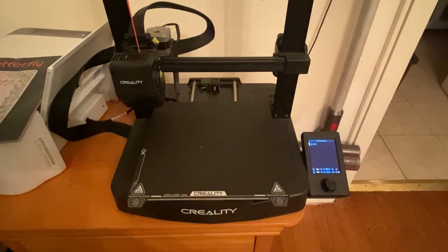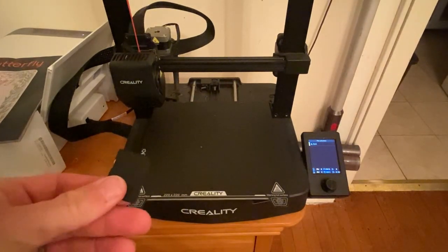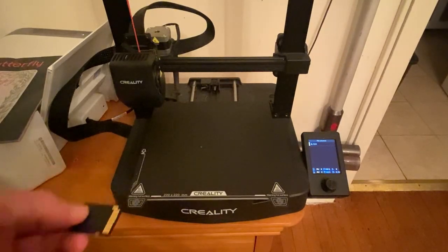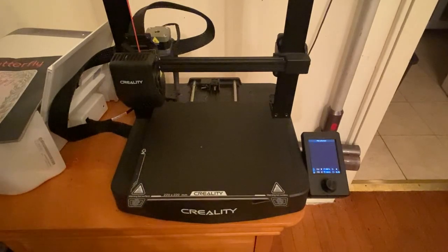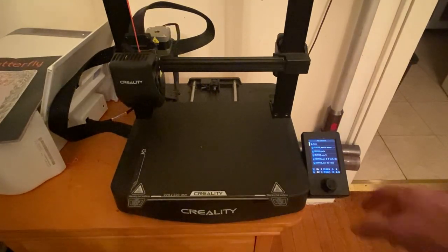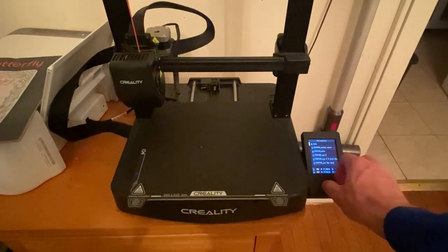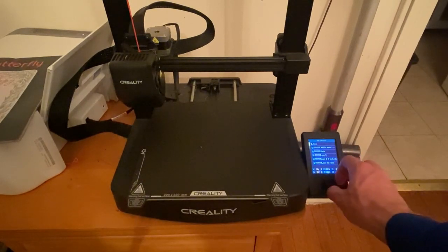Once you've sliced your file, you can come up to the machine. Okay, so this is again an Ender 3 V3 SE. This is the one I have at home, but it's exactly the same as the one in the machine shop. Okay, so you take your flash drive. You have to stick it in teeth up into the machine on the side over here. Okay, so you stick it in there, and it'll click in and stay. And then on the screen here, you should be able to navigate through it.